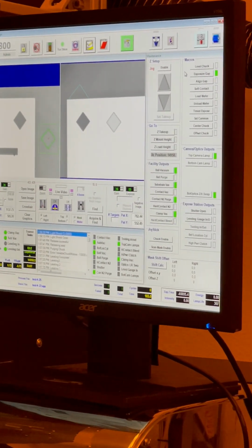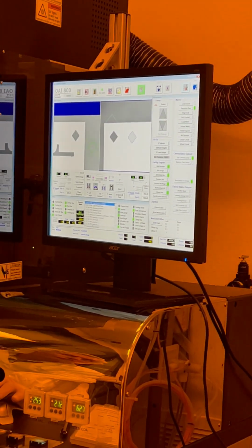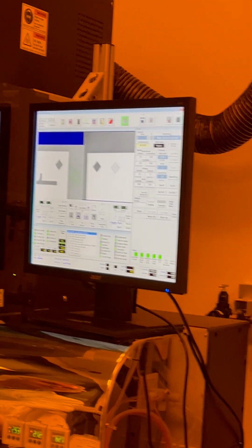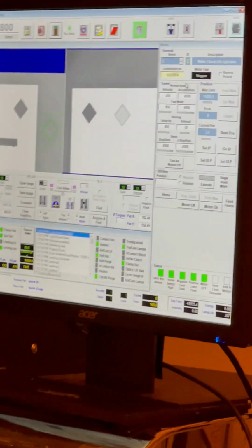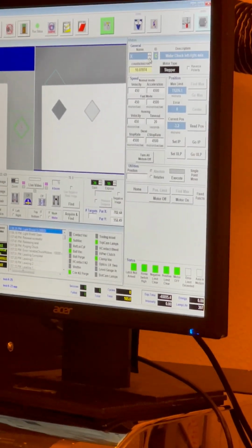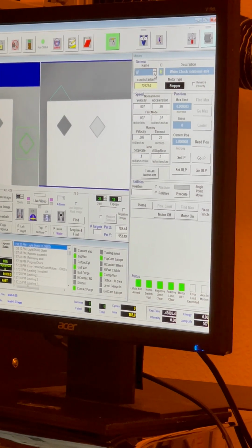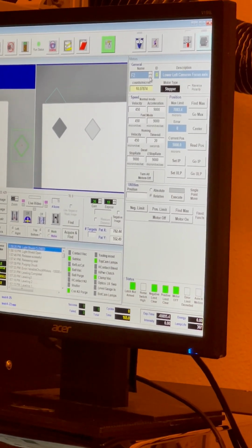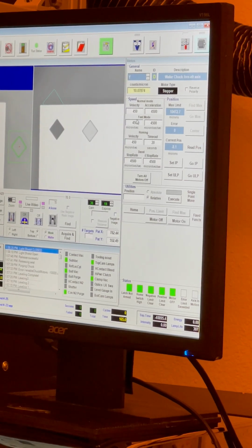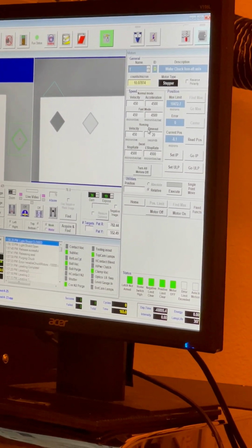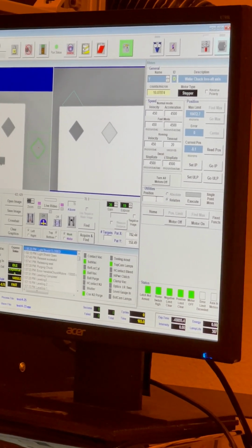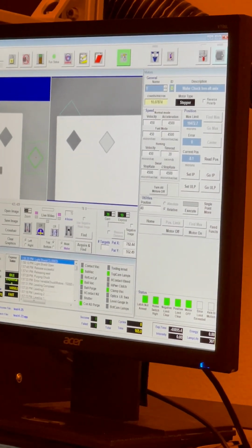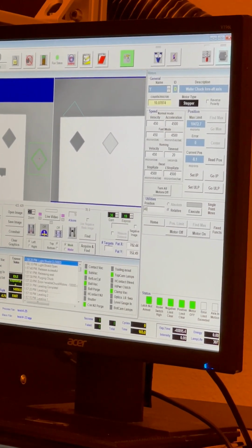I think there's not that much to it. I think we covered a lot. Over here, we're getting into some of the lower level stuff. You have a bunch of motor axes on this tool, and this screen gives you individual control of those motors. We have them labeled by letter, and you can step through them. They have all their velocity and acceleration settings. You can give them direction, like a relative move of 40 microns. It's all in microns, except for theta. Theta's in radians.